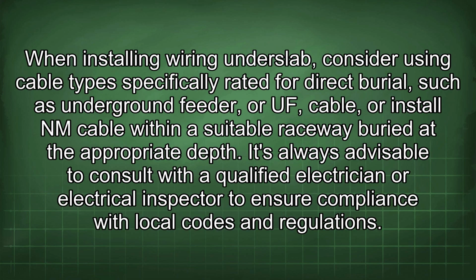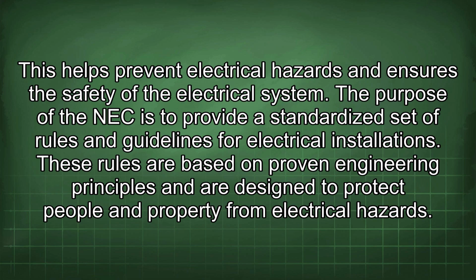When installing wiring under slab, consider using cable types specifically rated for direct burial, such as underground feeder, or UF cable, or install NM cable within a suitable raceway buried at the appropriate depth. It's always advisable to consult with a qualified electrician or electrical inspector to ensure compliance with local codes and regulations. This helps prevent electrical hazards and ensures the safety of the electrical system.